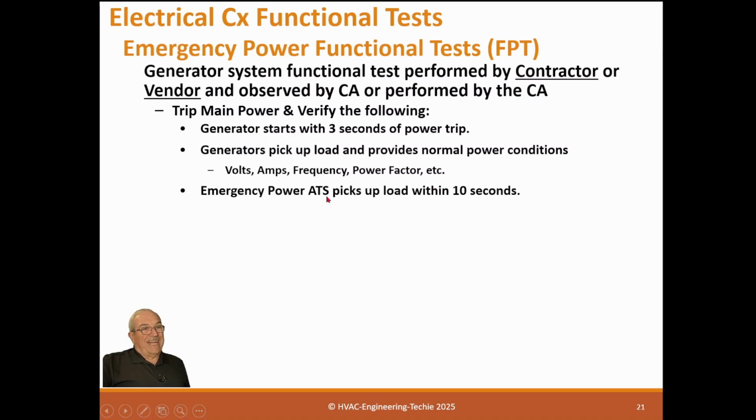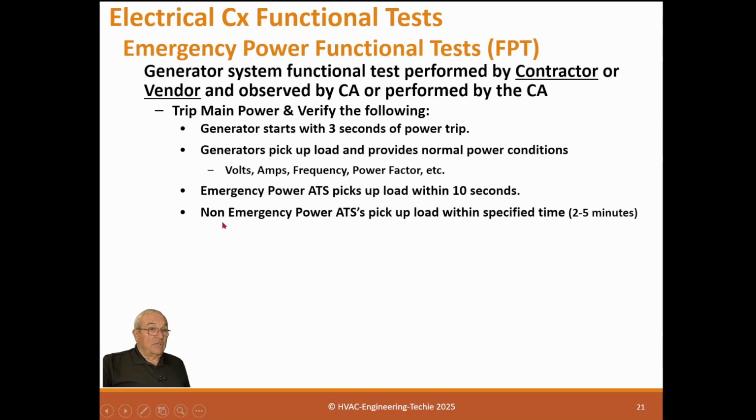Emergency power ATS, automatic transfer switches, picks up load within 10 seconds. So if it's an emergency one, that's required, 10 seconds. And normally this is emergency lighting loads. That's a code requirement. People can't be in the dark for more than 10 seconds. That's what the code says.